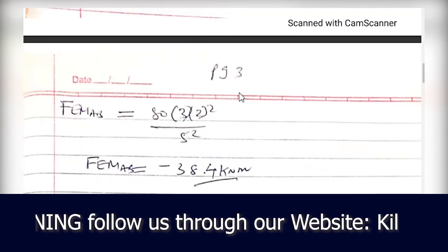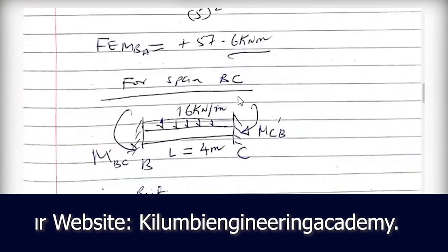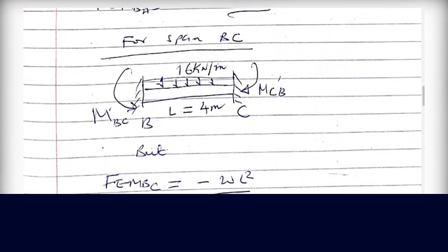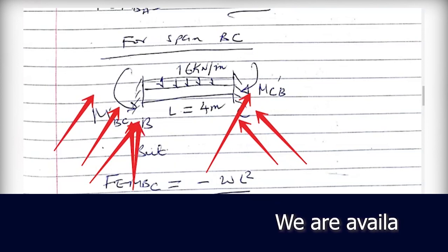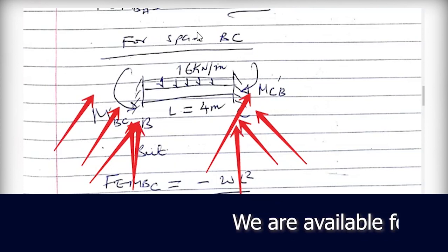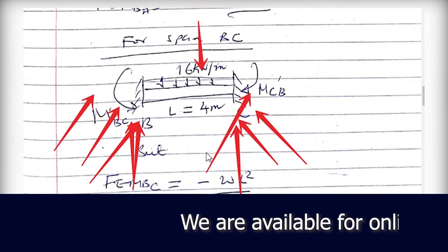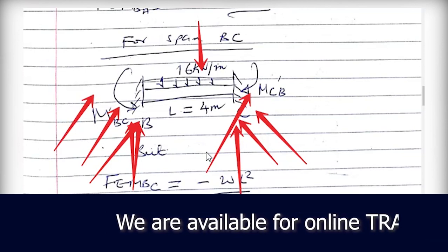As I said here, at equilibrium, because you have this value and this value, taking moment at this point you can get the reaction here, and taking moment at this point you can have the reaction there. At equilibrium, the reaction RA and the reaction RB should be equal to the load applied at the center.